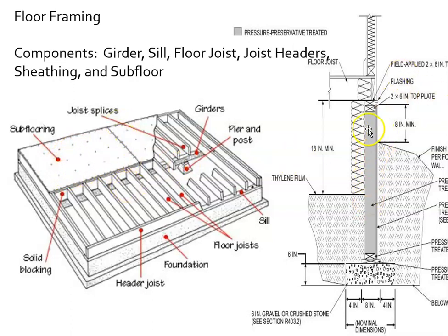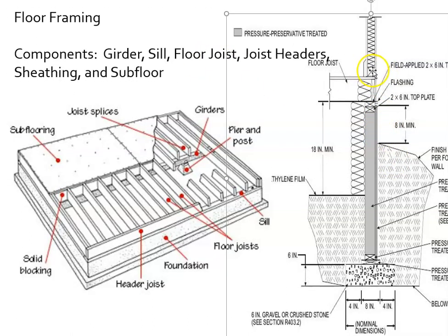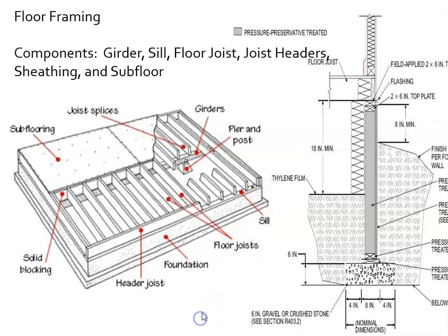All right, and then here we'll pretend we have our foundation, pressure treated sill, joists right there. That would be our rim board or header joist. And when we look at these details and we see a rectangle with an X through it, like we see right there and there, that means it's a continuous board. Same with that one. And I don't know what this is. I should really get rid of this detail. It's really kind of goofy, like that square block. That's not what it looks like typically. But we'll see other better examples coming up.